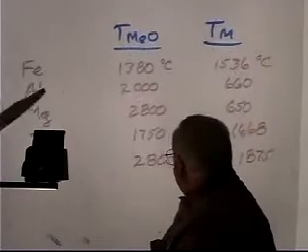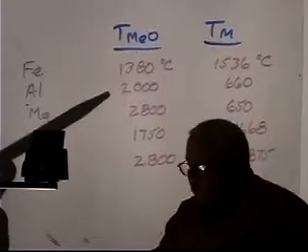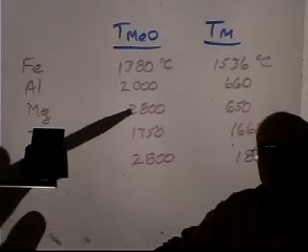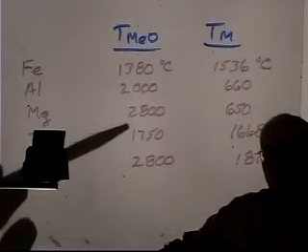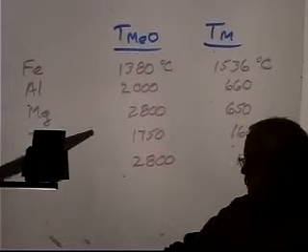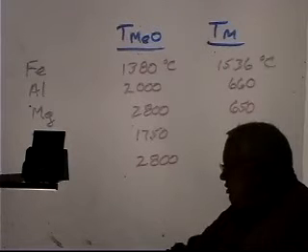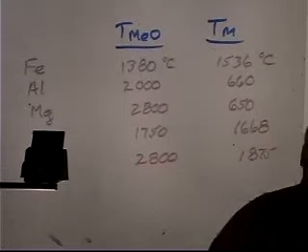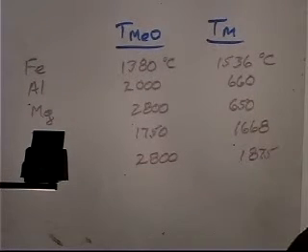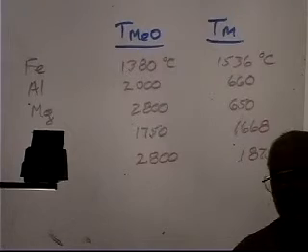Now, you can't burn aluminum because the oxide melts at a higher temperature than the metal, and so you can't blow it away. You can't burn magnesium for the same reason. Chromium, or stainless steel, which contains a fair amount of chromium, you cannot oxyacetylene cut or oxy-fuel cut because the oxide melts at too high a temperature. Now, titanium, in theory, you should not be able to cut, but in fact, we can.